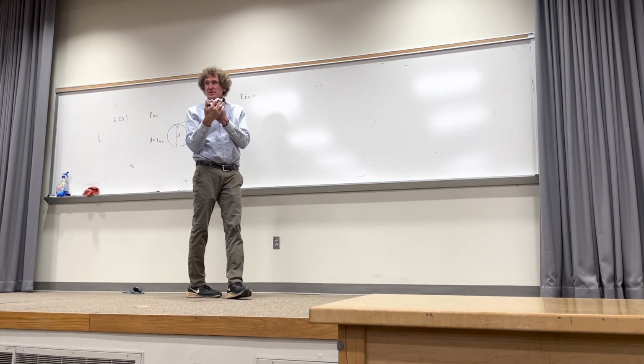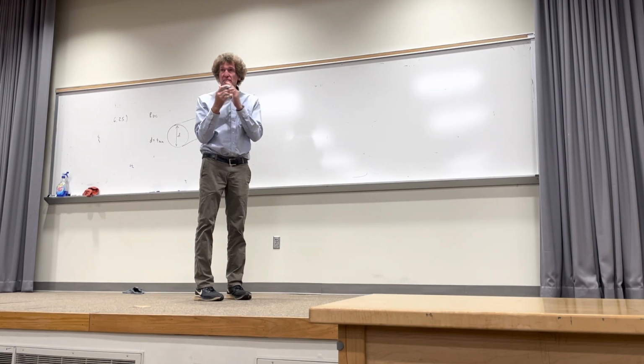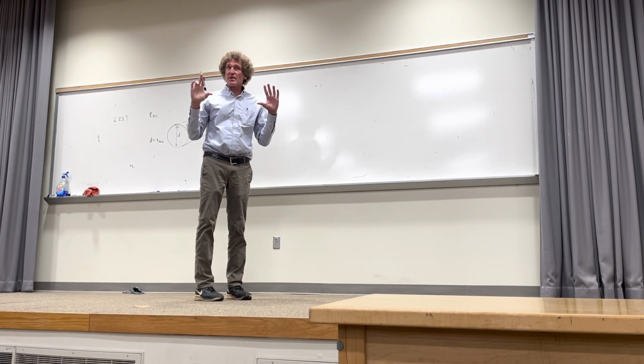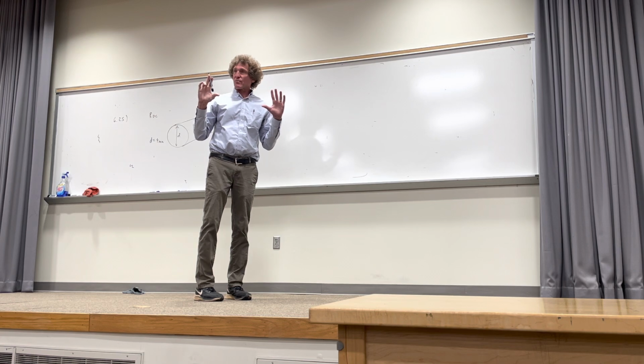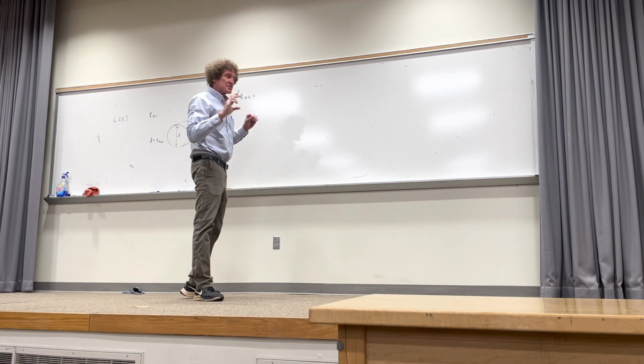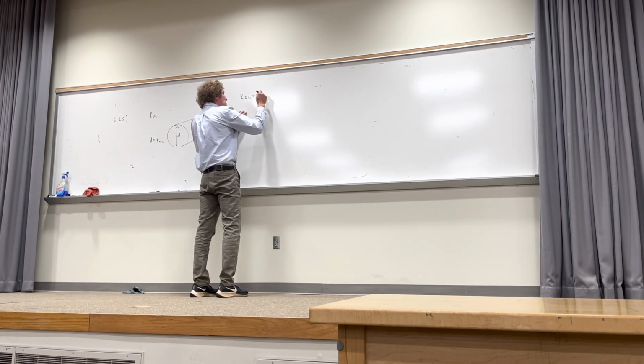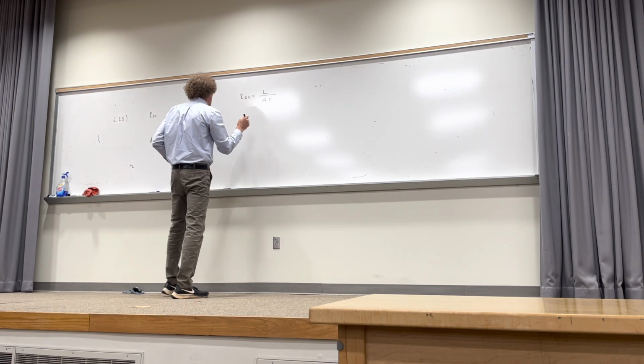If the cross section does not change versus length, it doesn't matter the shape of the cross section. Y'all hear me on that one? Doesn't matter if it's square, round, elliptical. The only thing that matters is the area. So it's always proportional to length, inversely proportional to area, and inversely proportional to sigma.